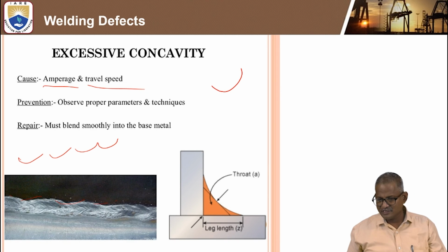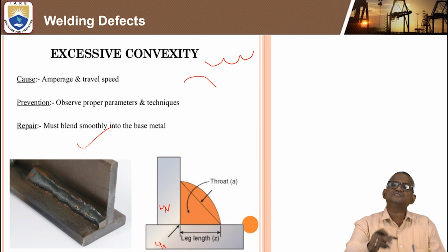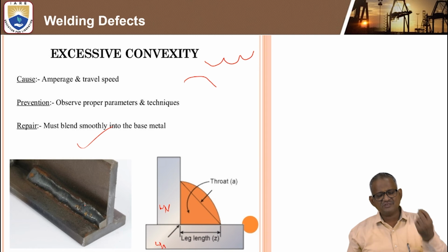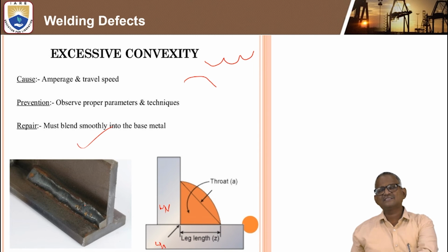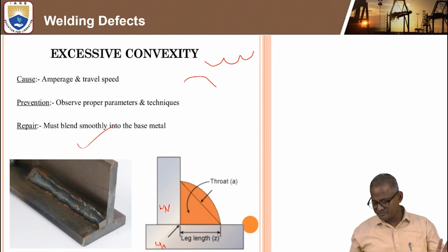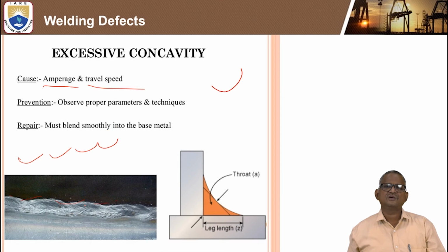But in this convexity, again chipping hammer, chipping metal can be used to remove all those things. Within a fraction of time after performing the weld, immediately you can take the chipper and do it. Otherwise, it cannot be removed by anybody. This is the best thing only.